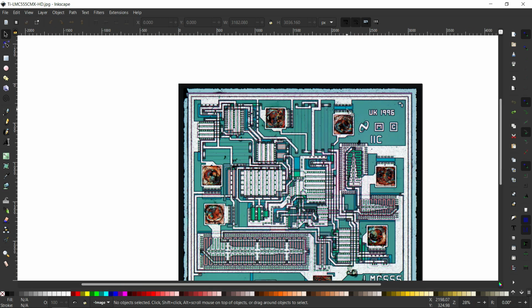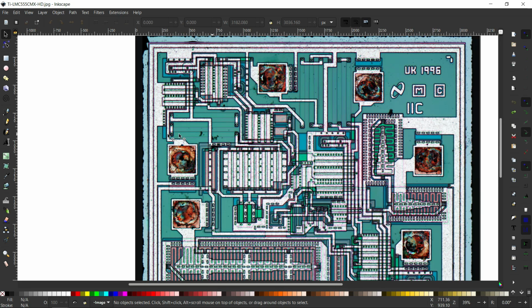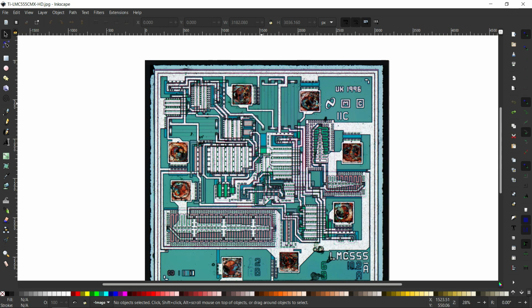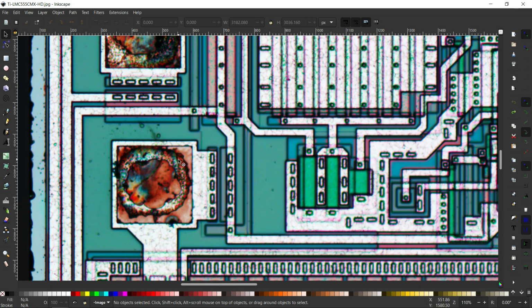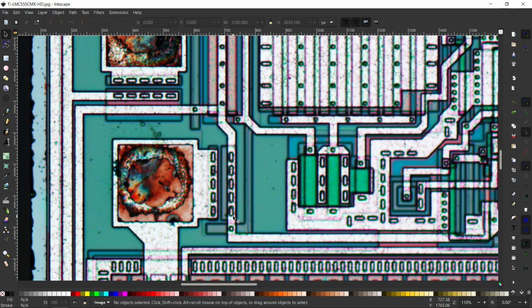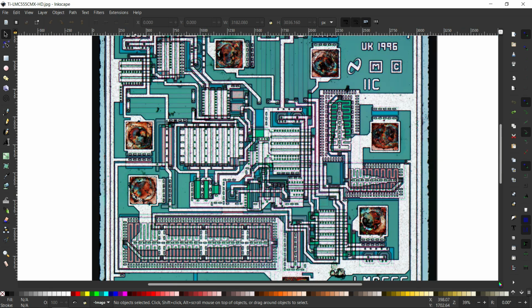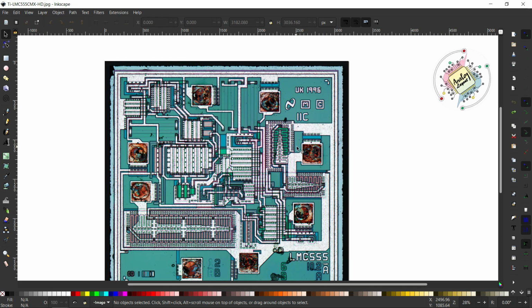In the same way, we have totally 8 pins in the diagram: first pin, second, third, fourth, fifth, sixth, seventh, eighth. Totally we have 8 pins because it's a dual in-line package. See, wherever you go and see the pad, all the pads will consist of one diode. So this diode is usually used for ESD, because this dual in-line package, that is called a DIP, right? So this DIP will be handled by a human.